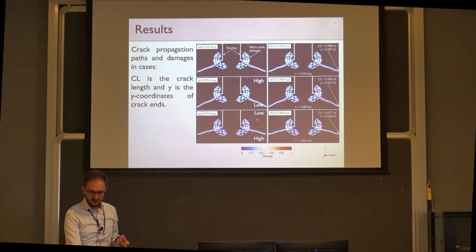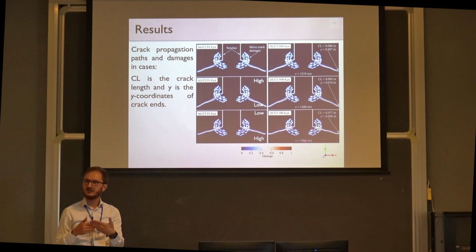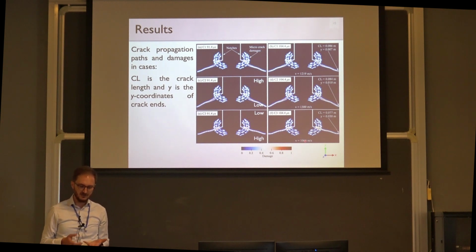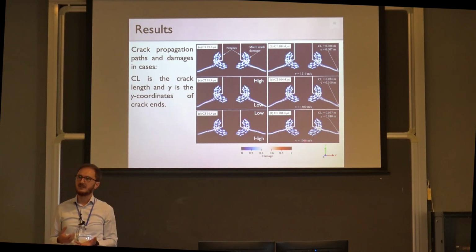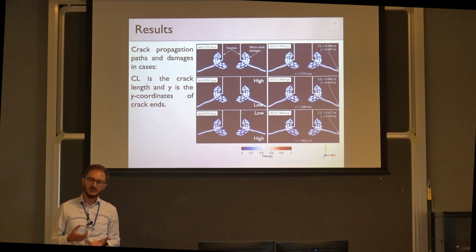When comparing case 1 and 2, the average velocity values increase a little bit. However, the velocity is significantly lower in case 3 when you change the direction of the gradation of the material properties. This difference means that the direction of material gradation plays an important role in the toughening mechanism. It's very important to crack propagation velocity.